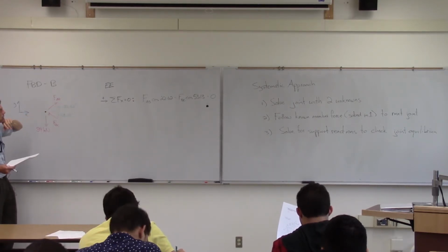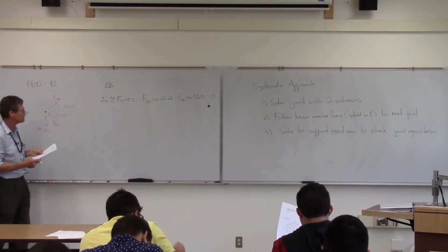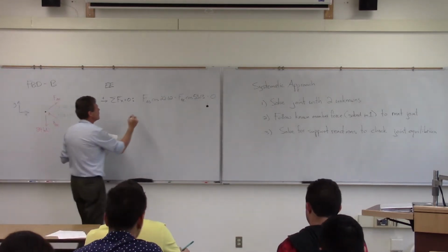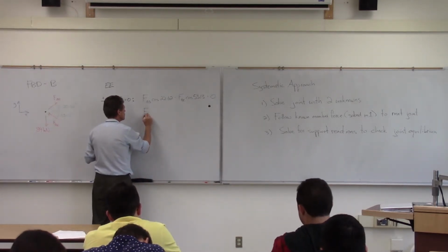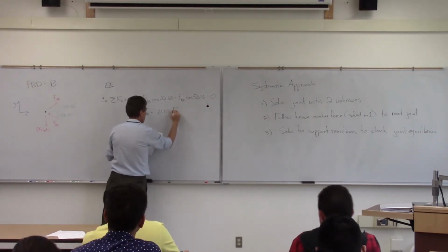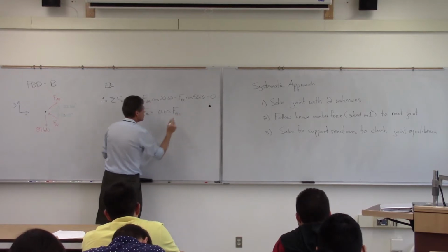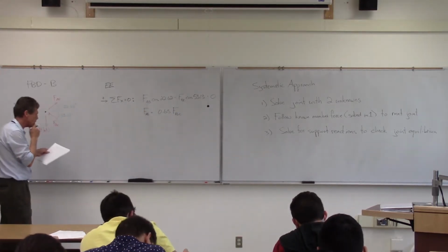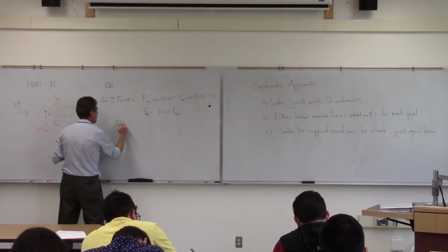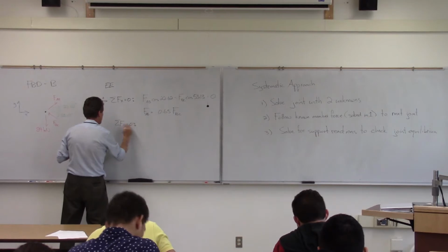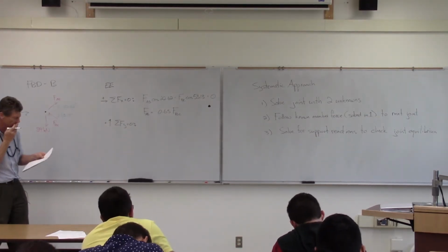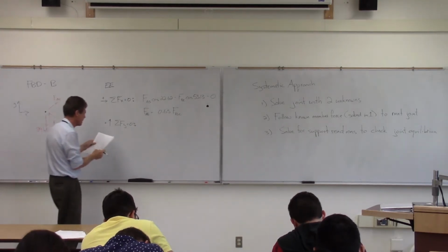You've chosen a direction now, so when you start plugging things into your sum of forces x, sum of forces y, you've got to apply them in the correct sense there. So the A is going to be positive, the BC portion is going to be negative per what I've drawn with those arrows. And then when I get done, I'll be ready for substitution because I'll have FAB in terms of FBC. So straightforward calculation there. And again, I'll set up my next equation, choose a positive direction. In this case, I'll choose it with the positive y.